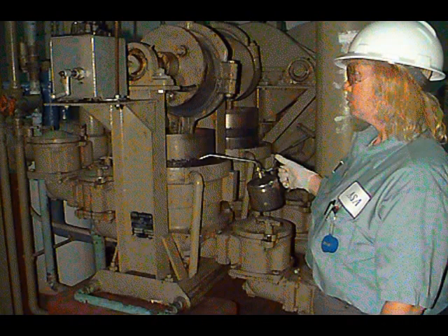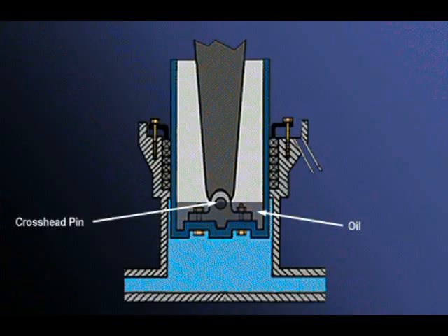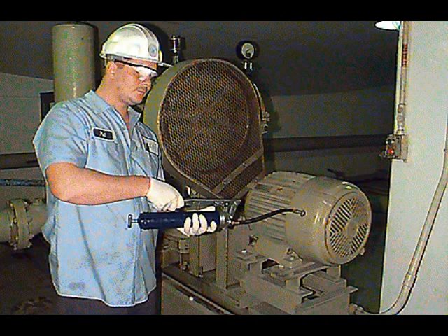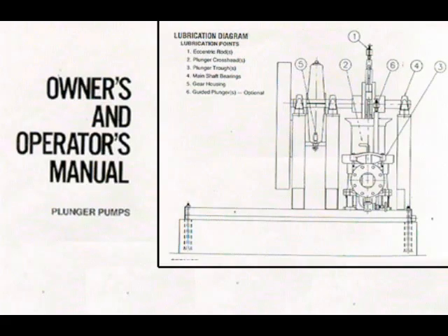Number 2. Plunger trough. A small quantity of SAE 90 gear oil in the trough of the plunger provides lubrication and increases service life. This can be added periodically to the top of the stuffing box around the packing during operation. 3. Plunger crosshead. Fill the plunger as required to cover half the pin with oil. Other points requiring regular lubrication are belt drive, chain drive or gear reducer, bearings, and motor. Again, refer to the manufacturer's recommendations for specific instructions about lubrication requirements and schedules.